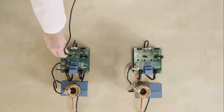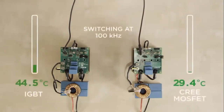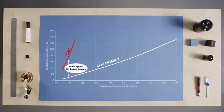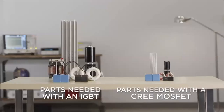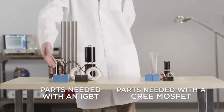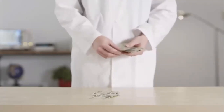Need proof? Take a look at these two identical Cree evaluation kits. They are both configured to run as boost converters, switching at 100 kilohertz. Look at how fast the IGBT is heating up. That's the result of the 6 times higher switching losses in the IGBT. And high IGBT switching losses mean that you need to reduce the switching frequencies, which results in larger parts, like inductors and capacitors. And larger parts mean a lot of extra money.